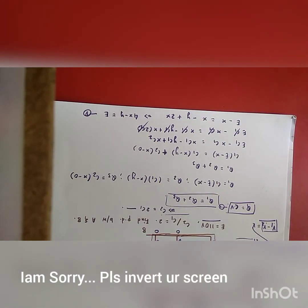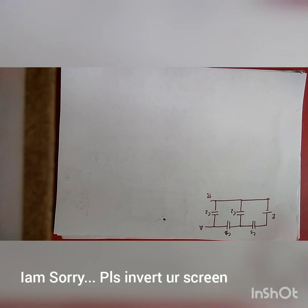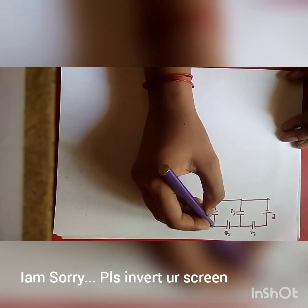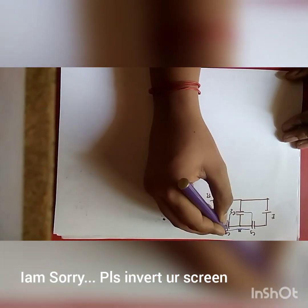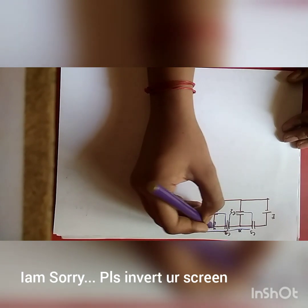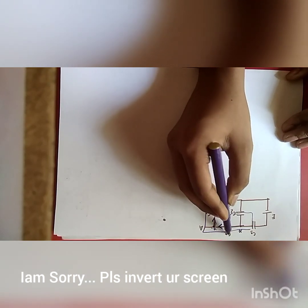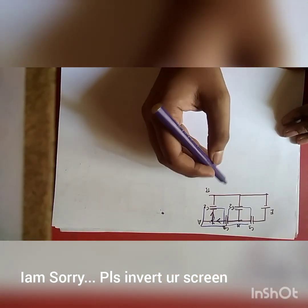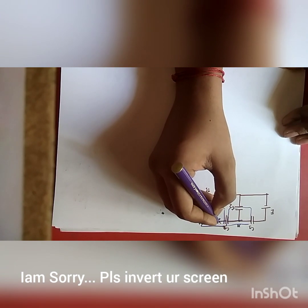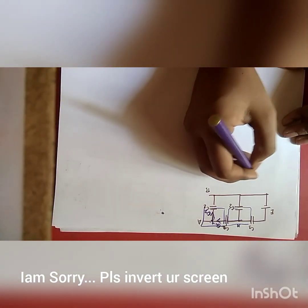Now we have to solve for another equation in the same manner and get the value of Y. So I drew that diagram again for your comfort. Let us continue our problem. Now we consider another junction. For this system, the potential is X, and for this system, the potential is Y. So now we apply KCL for this junction. Current coming in is equal to current going out. So current coming in through the second capacitor C1 is equal to the current going out through this capacitor C2. Applying Q equals CV and Kirchhoff's charge law again, let this be Q1 and this be Q2. Q1 equals Q2, simple.